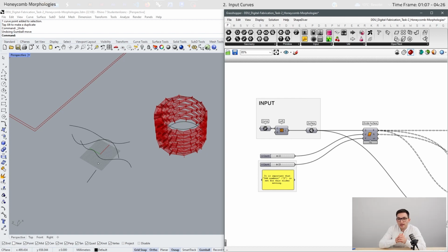As in the example by Andrew Kudless, two walls can be created next to each other that support each other. If you want to create the geometry from two parallel walls, it's important that the second surface is flipped, so that the normal vectors are pointing in the other direction. This allows the input curves to touch without the output geometry eventually intersecting.